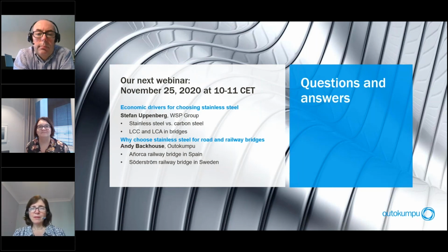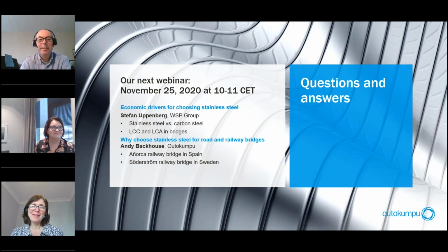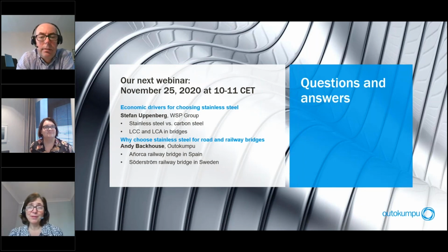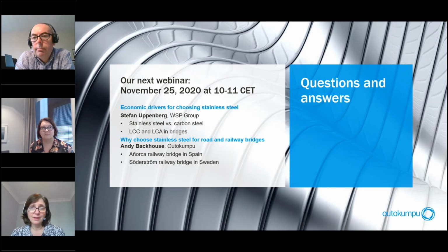Starting with the last question, yes, for construction in Europe you have to specify EN 1090, and that in itself points to the relevant specs regarding welding ferritic, duplex and austenitic stainless steels.